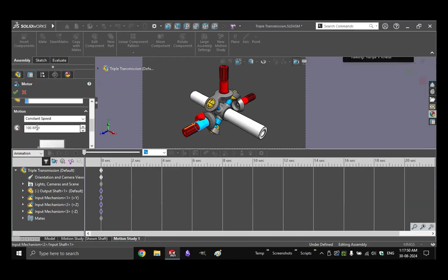And when it comes to the speed, it's set to RPM, revolutions per minute. How many revolutions is it going to do in 1 minute? And once again, I don't like to do math, okay? So I'm just going to say, revolutions per minute, that means that if it's per second, it's going to be divided by 60, right? So if I enter 60 revolutions per minute divided by 60 is 1 revolution per second, okay? So 60 is the baseline. If I want it to be in 2 seconds, I'm going to go with divided by 2, which is like 30 RPM. If I want it like in 4 seconds, it's going to be 60 divided by 4 and so on. This is how I think when I do something like that. So let's go with 4 seconds. 60 divided by 4, hit enter and hit OK.